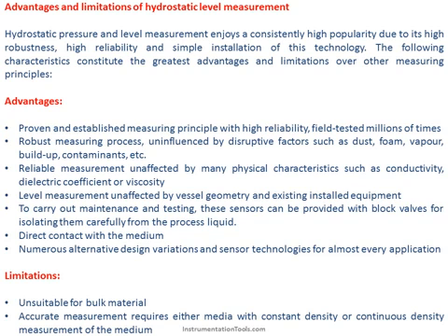Advantages and limitations of hydrostatic level measurement. Hydrostatic pressure and level measurement enjoys a consistently high popularity due to its high robustness, high reliability and simple installation of this technology. The following characteristics constitute the greatest advantages and limitations over other measuring principles. Advantages: proven and established measuring principle with higher reliability, field tested millions of times. Robust measuring process, uninfluenced by disruptive factors such as dust, foam, vapor, buildup, contaminants, etc.